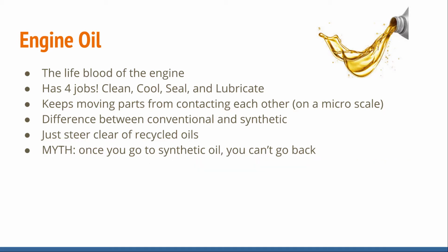Once you go to synthetic, you cannot go back. Not true. Everybody has different theories about that. Oh, it conditions the rubber, the seals will always leak, and oh, my engine's knocked before when I've used synthetic. That's not true. I wouldn't recommend switching back and forth on a regular basis, but it's definitely not the case. Synthetic oils all work the same way. You're not affecting anything by switching one way or the other.